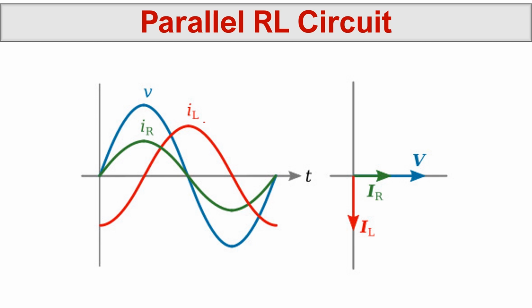So now we are able to read a phasor diagram. Look at here, this V and IR are in phase, because they started at the same point and ended at the same point. They get the peak at the same time. If we draw the line, the peak is falling on the same line. So it's showing the same behavior. So V and IR are in phase.